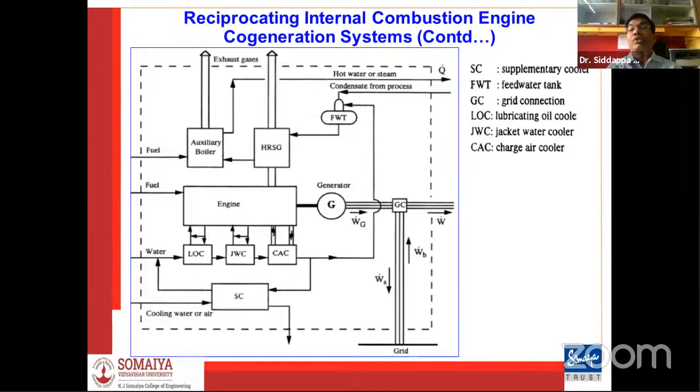Almost if it comes down to 40 or 50 degrees centigrade, but you are not allowed to, if it's a harmful gas or a CH compound containing gas, leave it to the atmosphere, because the products of CH compounds may be H2O and CO2, which are not harmful, but also NOx, other polyaromatic hydrocarbons and particulate matter, which are harmful to the environment and health.